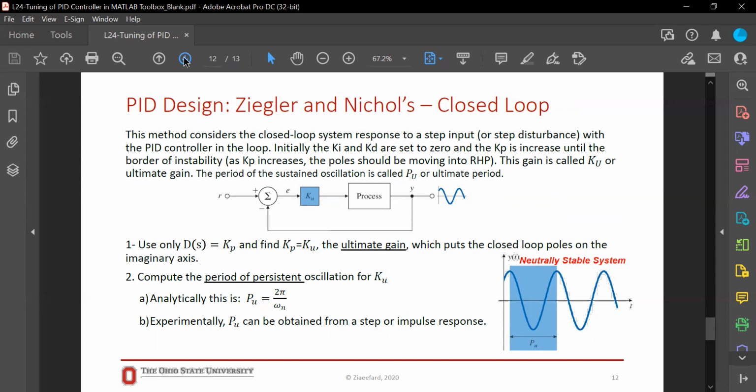And then from there, you will plot the response and you increase the gain until you see an oscillation. So when you have oscillation in your response, what does it mean? Where are the poles of your system? At least one of them is very close to or on the vertical axis, right? So we want to get to the point of instability.